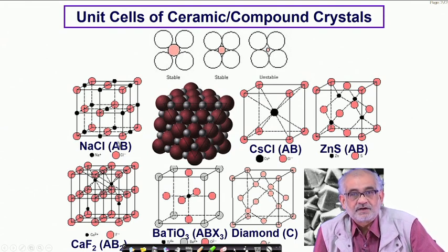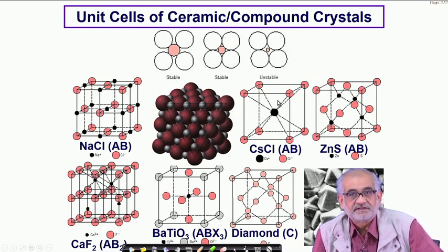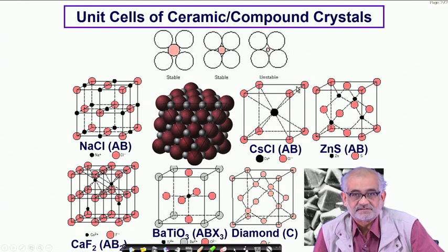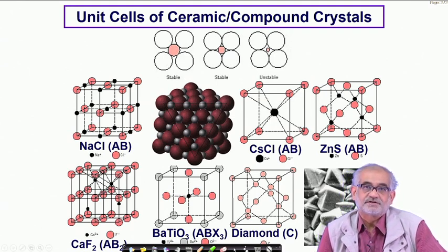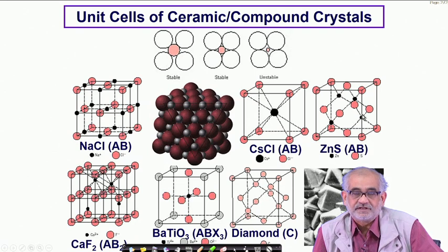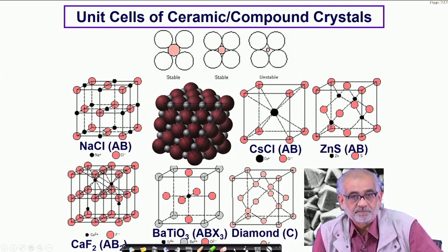This is how we can develop various compound crystals, ionic crystals, interstitial compounds, or intermetallic compounds, and so on, which will have characteristics different from, and somewhat in between, metals and nonmetals. When we talk of the structure or properties of solids and try to connect them with the structure, we should first understand that structures are simplest in elemental crystals, but fairly complex in compound crystals.